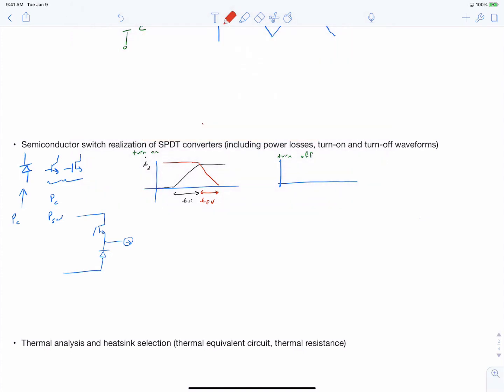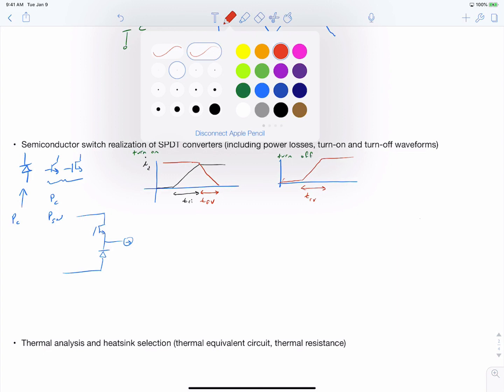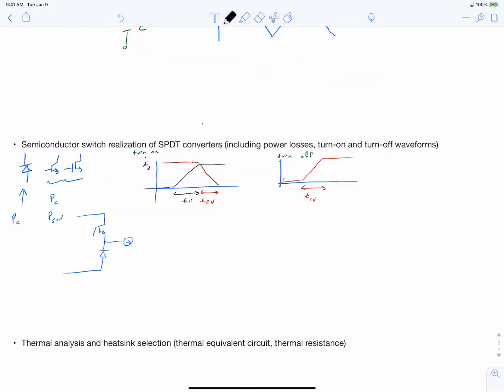First our voltage has to rise, termed a voltage rise time, TRV, and second, our drain current had to fall. And we showed on these plots how you can match this up to what the gate source voltage is doing, because the gate source voltage is what drives this entire phenomenon.